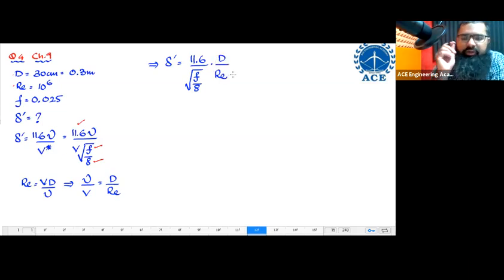Now please observe, he is asking you the value of delta prime in mm. 11.6 and 8 are constants, F and Reynolds number are dimensionless. If you take the diameter also in mm, your answer will be in mm.